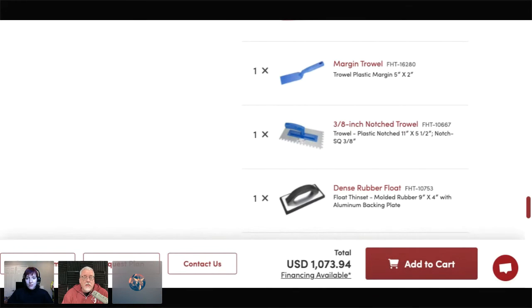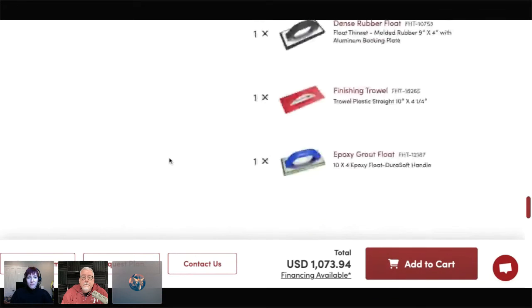But that's where the plastic comes from. That's why we do the plastic. And this is for people who may not have this job and have never done a floor installation before. They don't know which trowel to buy, what size margin trowel to use, or why to use a rubber float. That's to make sure you're putting the thin set over the cable without damaging it. Awesome point. Plastic all the way if you can do it.